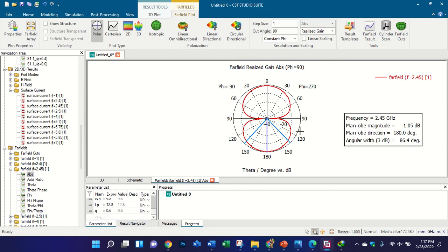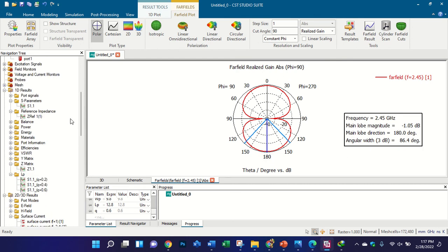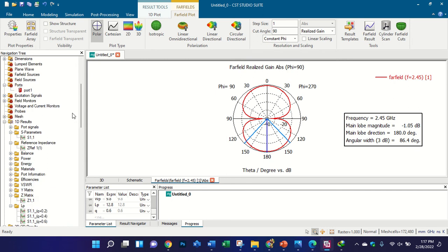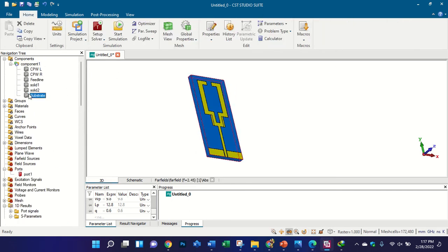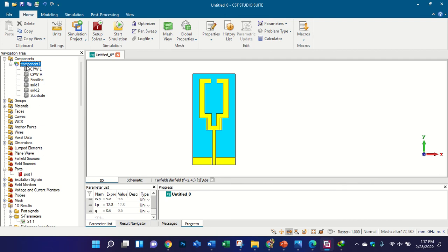I want you to design at 2.45 gigahertz using an FR4 substrate. I use FR4 because it is a cheap material and easily available everywhere, but if you use Rogers, then sometimes it is available, sometimes it is not. If someone achieves very good results with a good design, I will approve that design and tell them to save it for the coming papers.